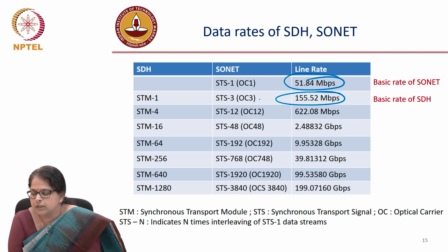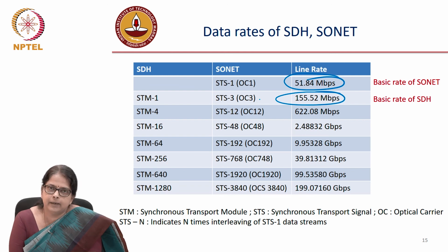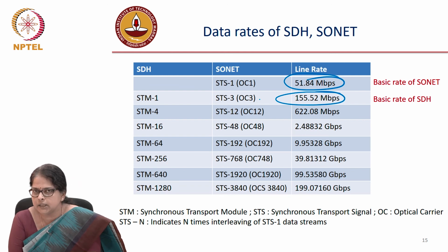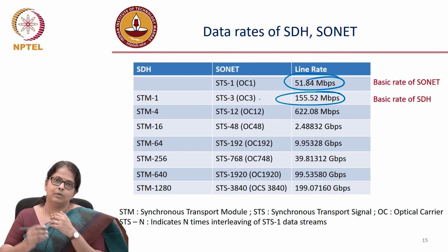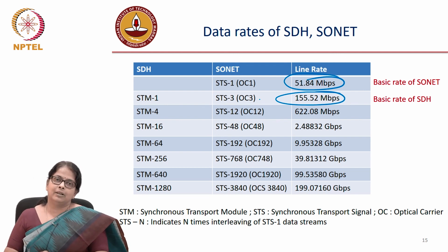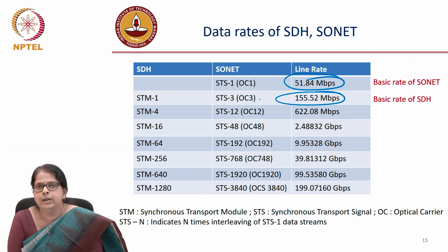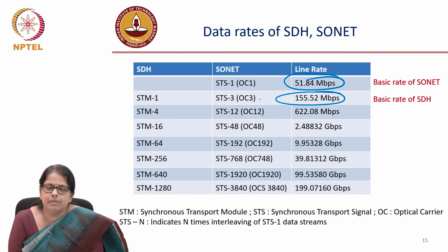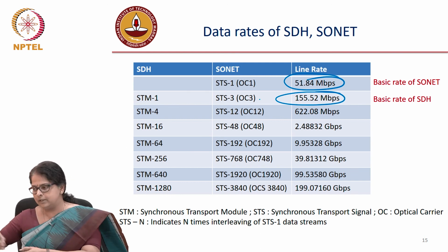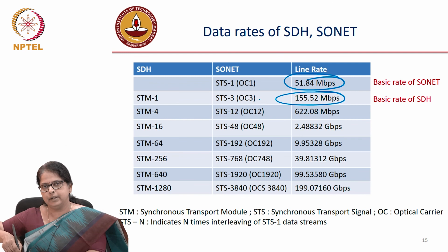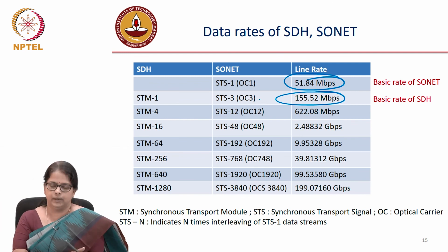We should start from data rates which are supported by both SONET and SDH, which means that in optical communication, the basic fundamental data rate that will work is only 155 Mbps. The standards require a minimum data rate of 155.52 Mbps. Okay, so there's no 10 Mbps link or something, unless you're doing it in your own point-to-point link where you're not trying to connect to a network.